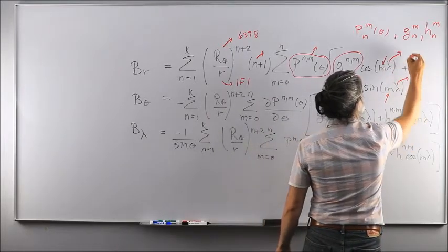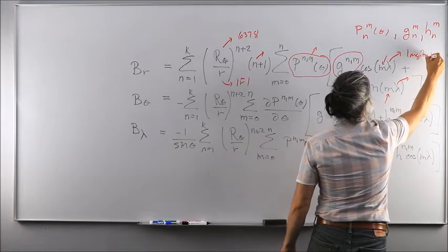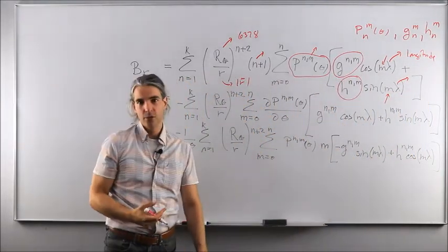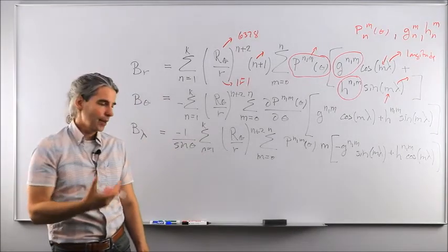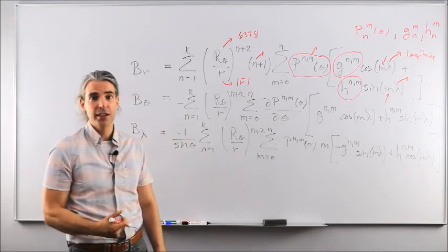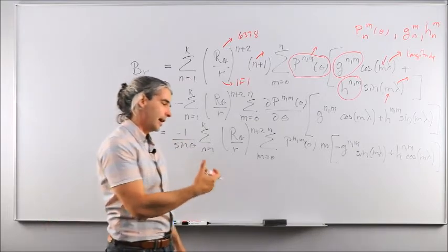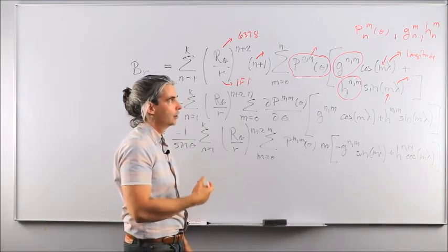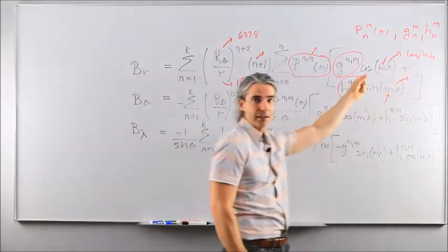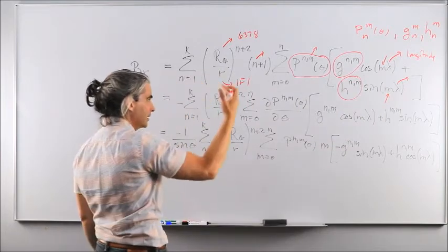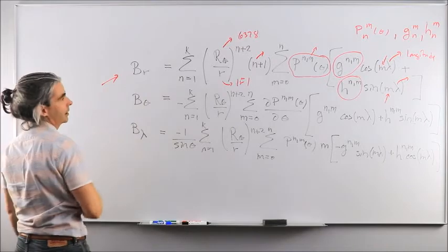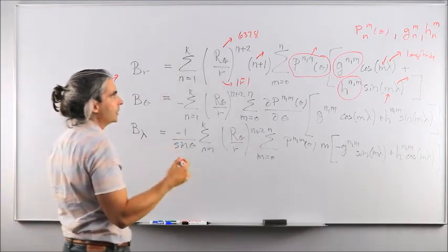Lambda is the current spacecraft longitude, obtained by solving the two-body equations, looking at the x, y, z components in ECI and turning them into the Earth-centered, Earth-fixed reference frame. That was our ECF reference frame. And how to go from x, y, z in ECF to latitude, longitude? Well, we have all the equations for that in orbital mechanics. So that is known or can be easily calculated. Although this looks terrible as it is, we have all we need to calculate it.